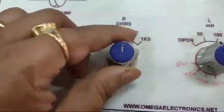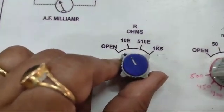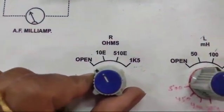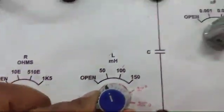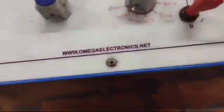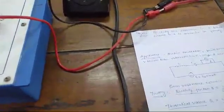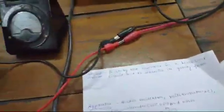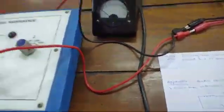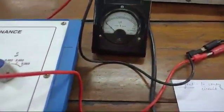Here are three values of R: 10 ohm, 510 ohm and 1500 ohm, and these are the L values and C capacitance values. So first we connect the circuit in this way. The audio oscillator is connected to this series and parallel resonance circuit, and a milliammeter is connected in series.